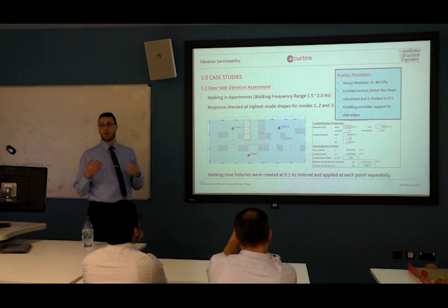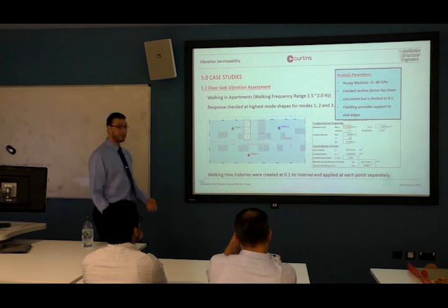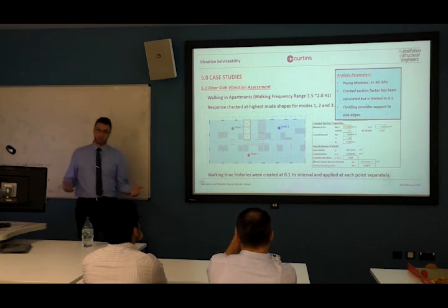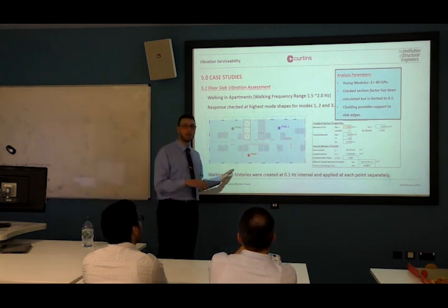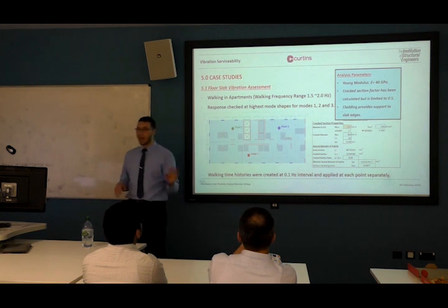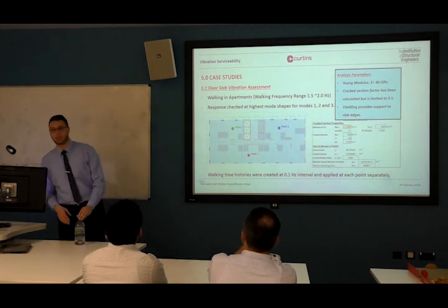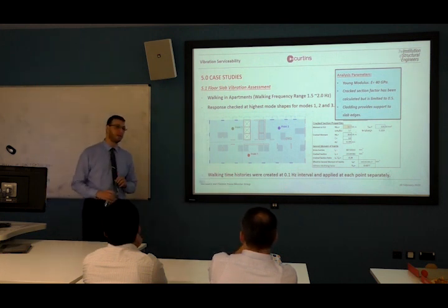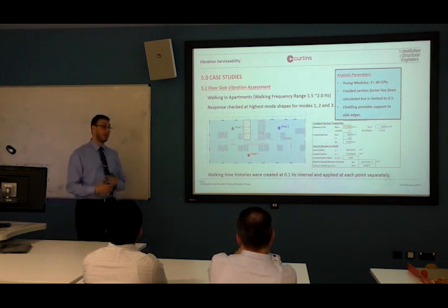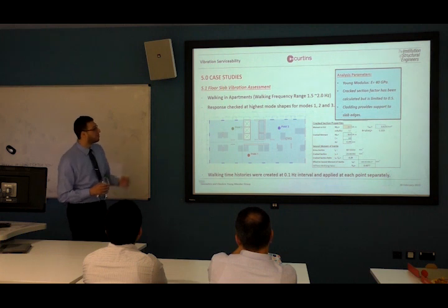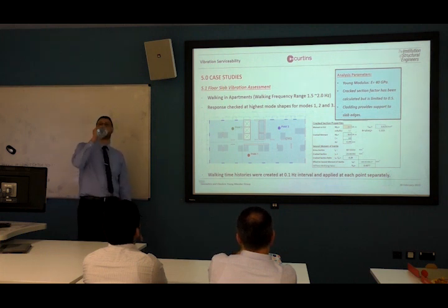Mass included in this analysis is the self-weight, finishes, dead load. Everything dead load can be included. Okay? You can take 10% of the imposed load, but you have to prove that it's there. I don't agree with this assumption, but sometimes you need it.